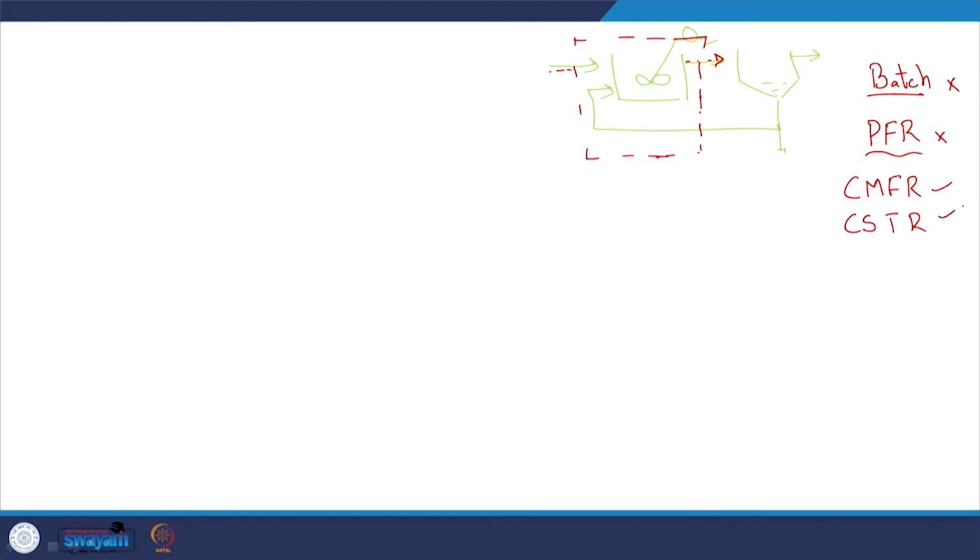So, we will apply the mass balance for this particular system, considering the system to be a CSTR or completely mixed flow reactor. What is the fundamental mass balance equation? Okay, not fundamental, the macroscopic mass balance equation. So, this is the accumulation term. How is the mass within the system changing, right? If dC by dt is positive, yes, it is increasing or accumulating.